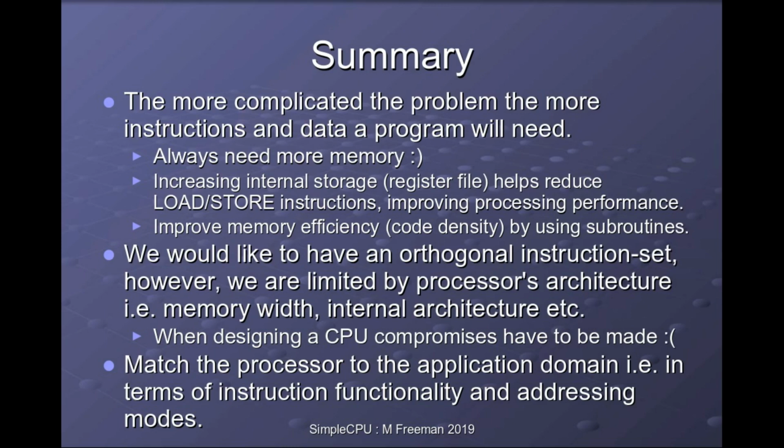When we design a processor, we've got some choices to make. Do we go for an orthogonal instruction set? Do we allow each instruction to use each addressing mode? Or do we put limits on it to simplify the hardware? That's very much a compromise to be made, depending upon the application domain of your processor and how much processing performance you need.